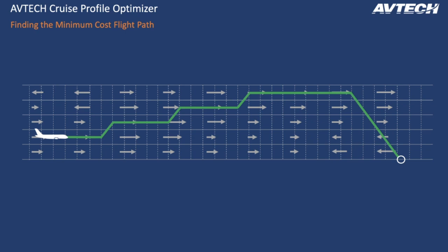The optimizer can be set to adhere to even or odd level restrictions based on the flight segments. So this is ATC restrictions. We can set limitations to the maximum altitude, so to apply a maximum altitude restriction based on the airline-specific operational procedures. The model can also be configured, and the minimum time between steps can be fine-tuned, so as to not allow the model to change level too often, even if it's more optimal. It may not be great for the pilots or ATC.